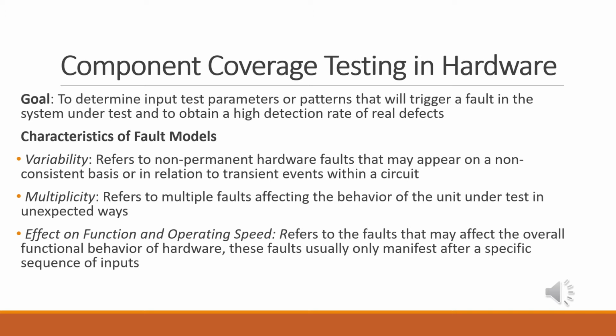Lastly, hardware test pattern generation techniques can be divided into the following categories: manual generation and pseudo-random generation. Manual generation is when test patterns may be generated manually by test engineers for functional verification. A model of the system should be simulated in order to verify the level of fault detection as well as to identify components whose failure has not been detected. Pseudo-random generation, on the other hand, is when test patterns are generated using a random number generator and then simulated at the circuit level. Usually, this technique is used early in the testing process to identify easy faults.